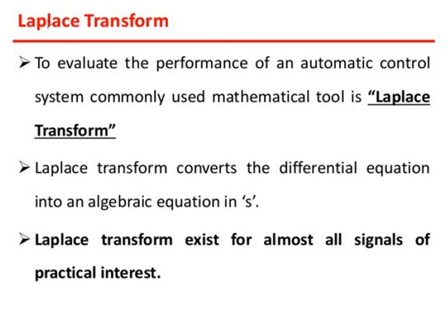Now what is the Laplace transform? To evaluate the performance of an automatic control system, a commonly used mathematical tool is the Laplace transform. The Laplace transform converts the differential equation into an algebraic equation in the form of s, and the Laplace transform exists for almost all signals of practical interest.